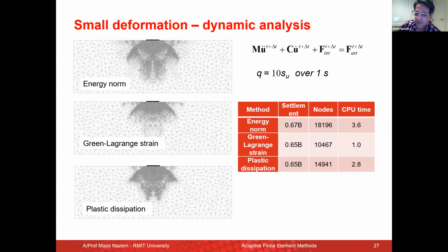Sometimes you have contact, you do remeshing, you remap the variables, no problem, but then you can't really satisfy the equilibrium equation and plasticity condition at the end. And if you can't do this, then you have to carry these unbalanced forces into your next increment. These unbalanced forces keep accumulating, and at some stage your analysis basically fails or diverges from the right solution. That's my experience, but I could be wrong. Yeah, no, this is a good point.